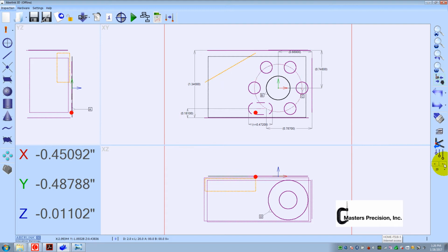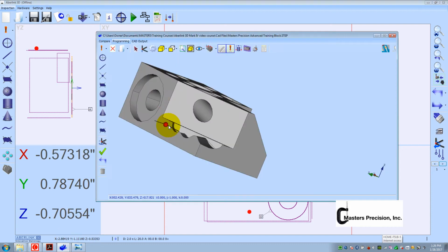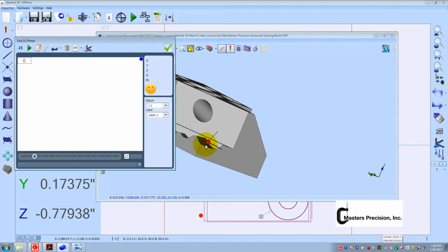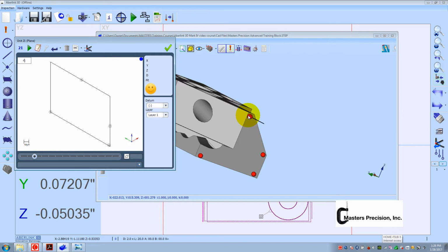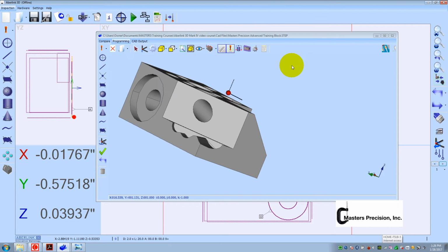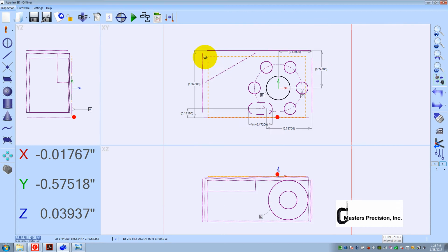There's the bolt hole circle. So I'm going to remeasure the plane right here. All right, so I've got the right stylus chosen. I'm going to choose plane. It might have feature predicted a line or something last time. I don't know what happened there. So now I can see my plane.